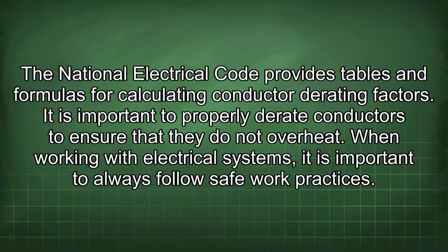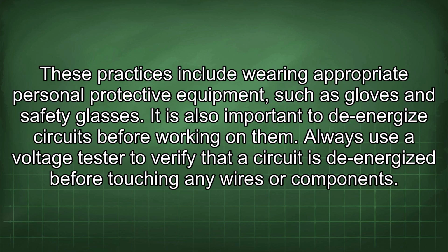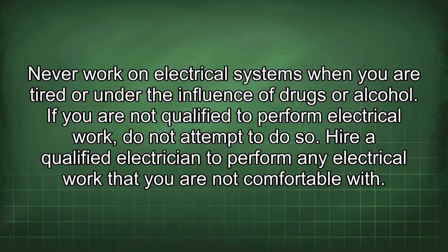When working with electrical systems, it is important to always follow safe work practices. These practices include wearing appropriate personal protective equipment, such as gloves and safety glasses. It is also important to de-energize circuits before working on them. Always use a voltage tester to verify that a circuit is de-energized before touching any wires or components. Never work on electrical systems when you are tired or under the influence of drugs or alcohol.